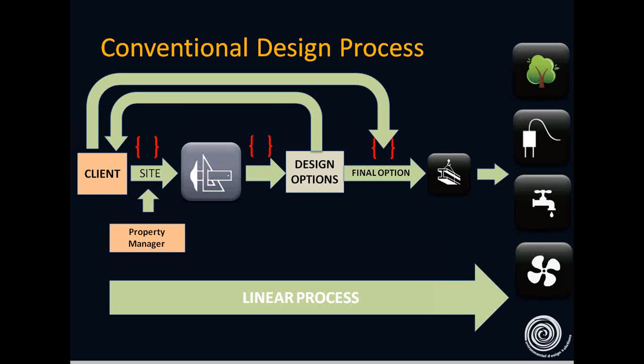In another example, the architect designed an institution building keeping in mind a VRV system. The design was approved by the board. The construction was started. When the HVAC consultant came on board, he suggested a central plant system to enjoy the benefit of diversity and thus lower capital costs. However, since the architect designed its planning keeping in mind VRV, there was no space left for AHUs and other mechanical rooms.